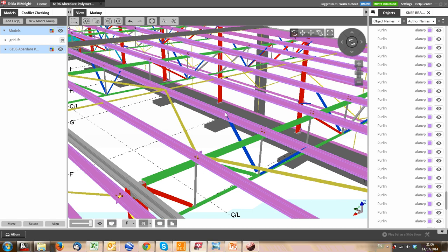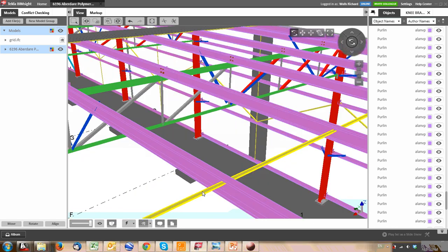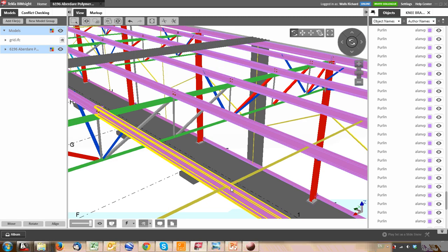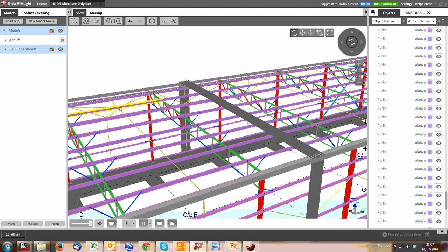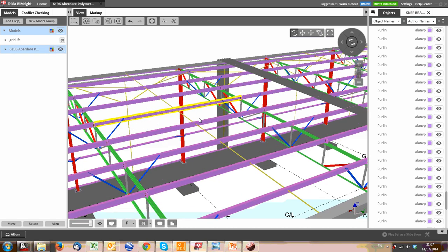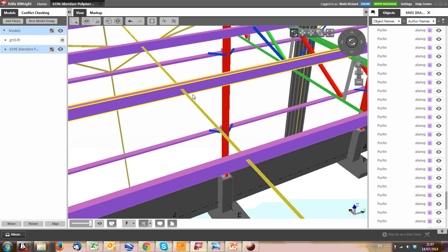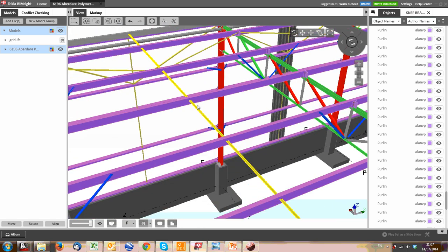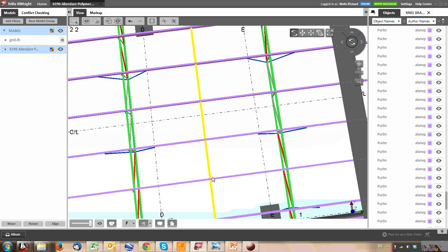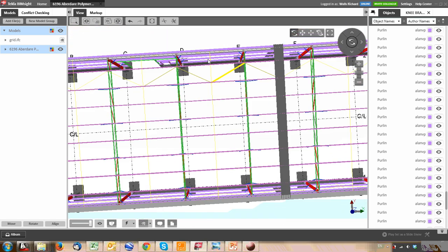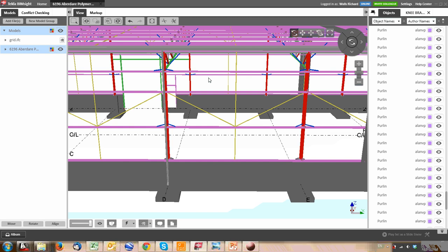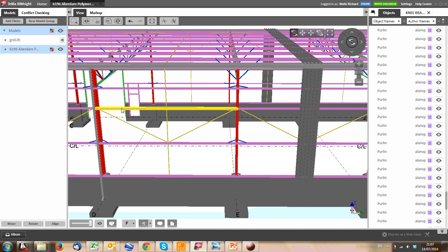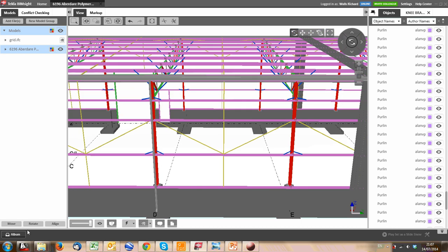The one nice detail you can do is rather than having individual pieces from one purlin to another, you actually put a long piece below the purlin with T's up. It's much easier for the fabricator to make because you don't have to have a lot of little pieces. You have one with T pieces, so it's sometimes also quicker to erect, but it just depends on the fabricator. So we're going to draw all these now. They, as I said, prevent the purlins from buckling or the girts from buckling. And also this diagonal prevents it from sagging when it hangs, especially on the girts. If you don't have these diagonals, you can actually see on site, especially on the longer bays, how your girts sag. And then when they do the sheeting, it looks terrible. So you put those in, at least everything is nice and straight then.